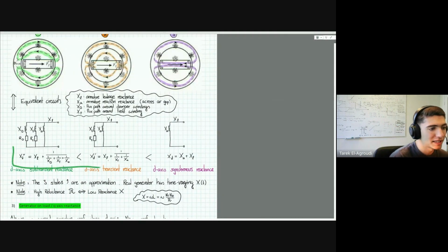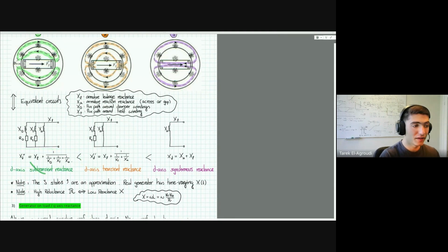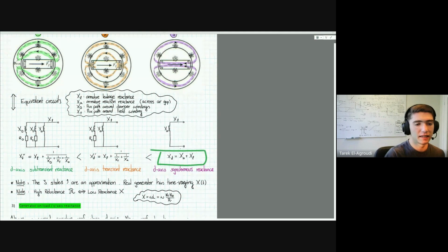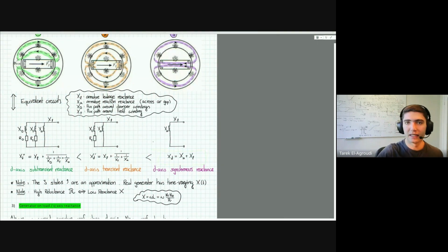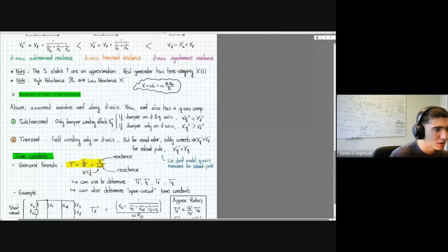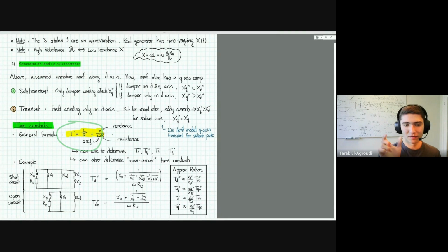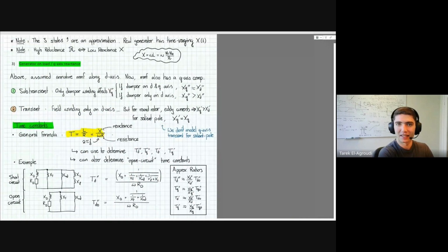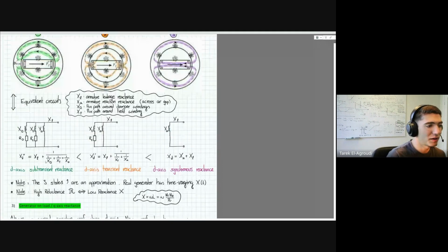That makes sense: your damper windings, which are very strong, decay very fast, so you have a very small reactance. Your transients are a bit slower, and your steady state, of course, is steady state. Furthermore, you only decay if there is resistance in this winding. And the damper windings are also built with a very high resistance. So this RD is very big.